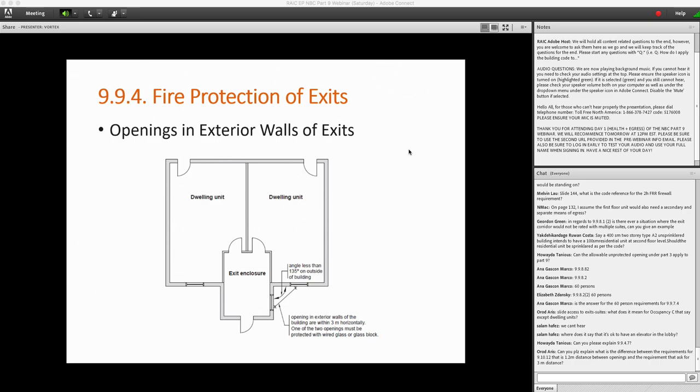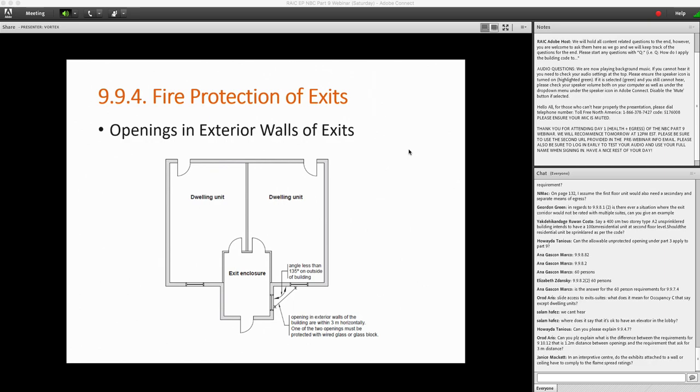Next question, still under 999: third floor egress, 1 meter above the third floor and 7 meters above adjacent ground. This will clash with guard requirements in the code. You need to have a restrictor so it is not openable. How do we solve this? I'll pause on that for a second.